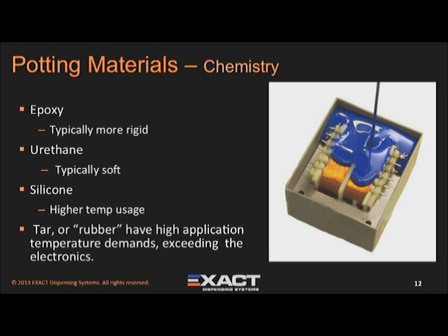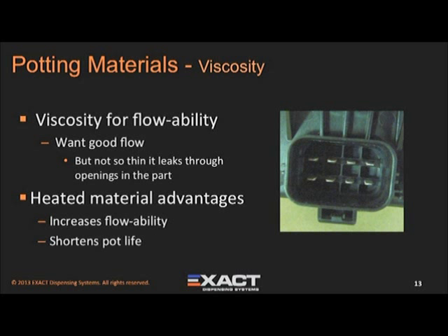What we do know, however, is that if you want a more rigid final part, an epoxy may be best. If having a part that is soft and flexible, urethane may be a better solution. If higher temperatures are being exposed to your part, then silicone is more likely the best selection. After you have selected the right resin, the thing we are interested in is the viscosity of the mixed material. To properly encapsulate, the resin must have appropriate flow, but not so thin that it leaks out of the part.